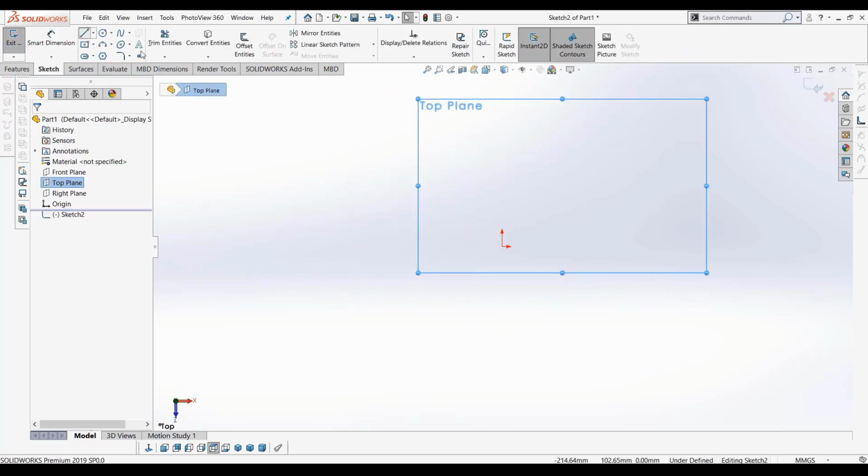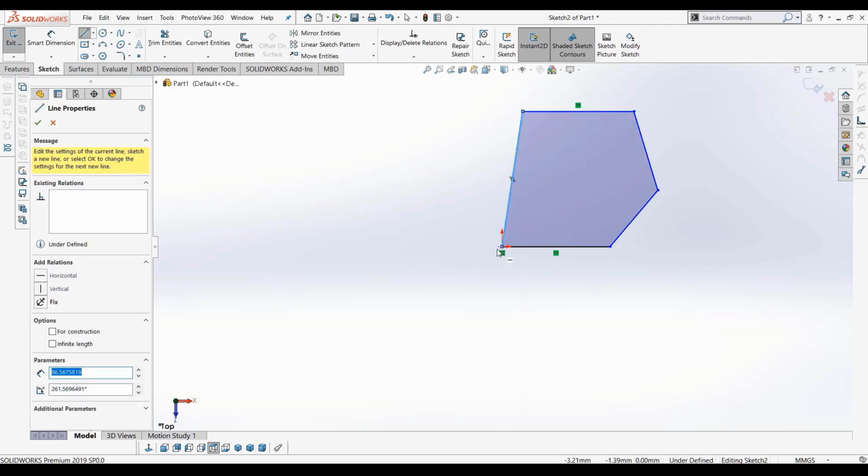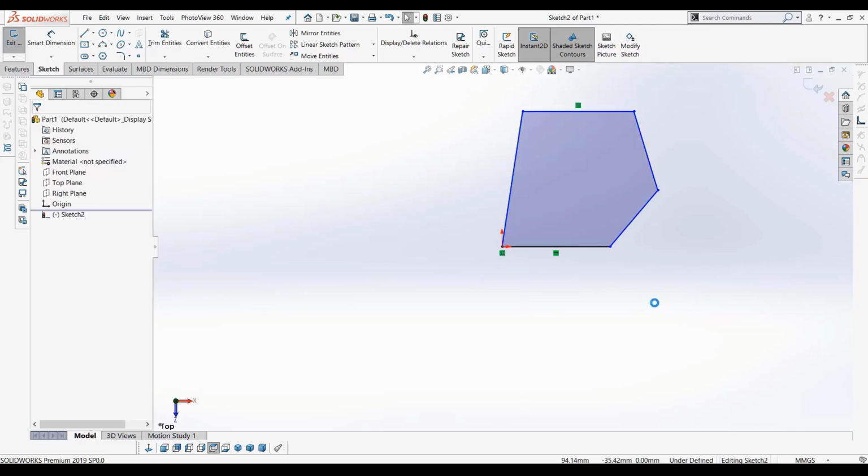Again, in the top sketch view, you see a series of colors. These colors actually mean that it says underdefined here. The blue color indicates that yes, the sketch you drew is here, and you can add features to it, but its specifications or components are not complete.